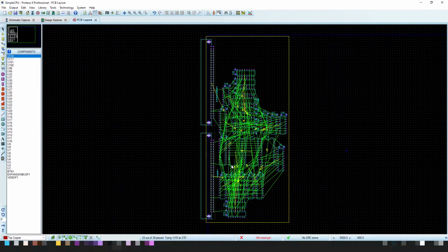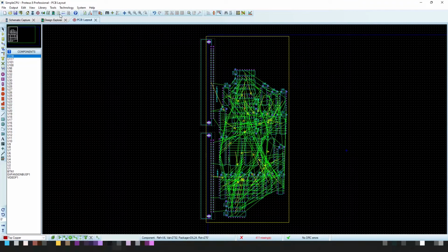There is a little bit of manual effort that is needed to create the output bill of materials and stuff like that. I mean, the bill of materials output generation here from the Proteus tool is usually good enough to give to PCBWay, but sometimes there are components and stuff like that that you need to manually tweak to make sure that PCBWay buy the correct component or use the correct package, or whatever. So anyway, generally speaking, this tool is a complete end-to-end schematic design tool, plus also layout design and auto routing if you like. But you can do it manually.